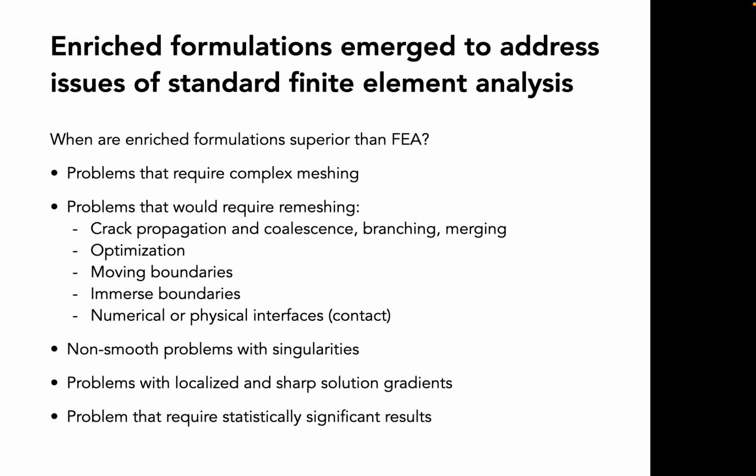Immersed boundaries: you can use enriched FEM to basically just immerse whatever domain within a bigger mesh, and then obtain the solution as if you actually had meshed the immersed geometry. And then, more recently, we have done some numerical or physical interfaces like contact.